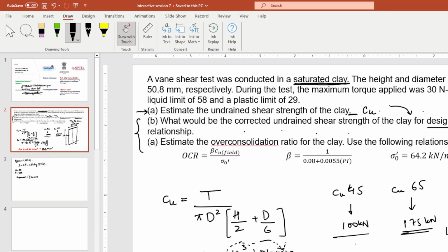In design, we calculate the strength of the material, and then we propose how much load this material can withstand. It is always better to be conservative, but not too conservative. If from this I obtain a design load of 175 and I put 175 kilonewton on this structure, it has a greater probability to fail than this structure, because I have provided a lower load here. Do you understand me?